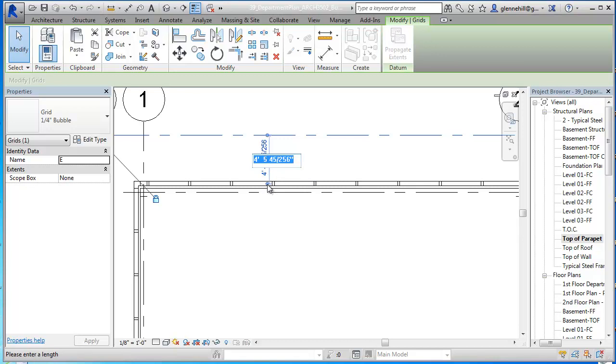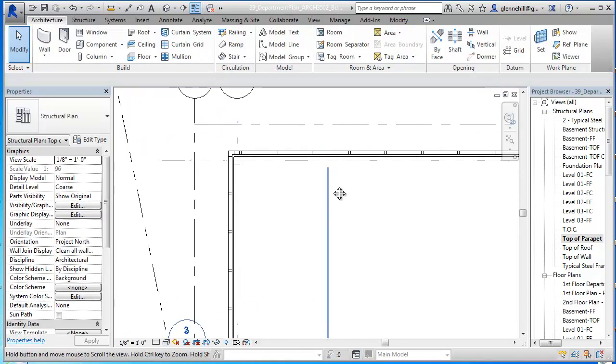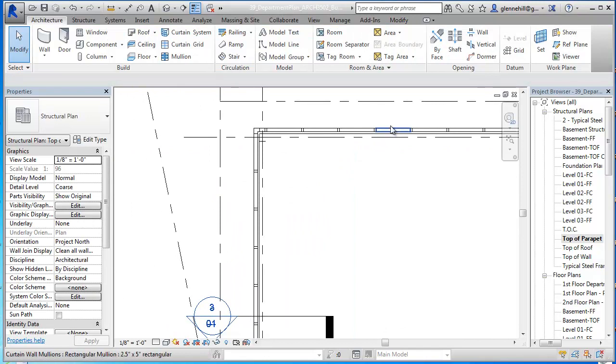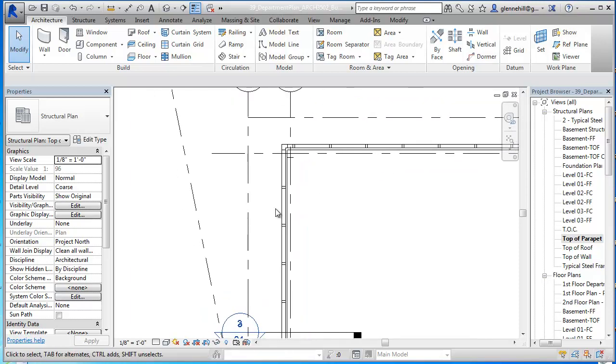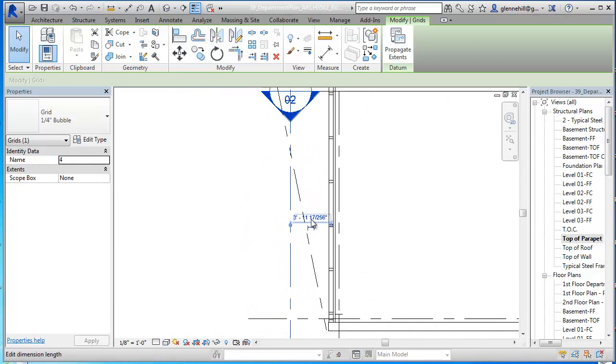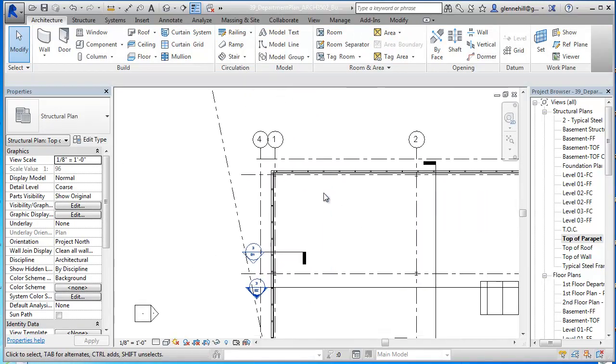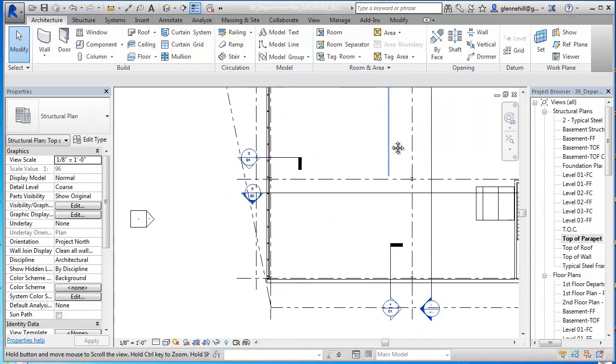I've got a little center line here to the window wall, so I'm just going to set that to 3 feet out from the center. So probably the clear distance is going to be around 30 inches or so. Now that may or may not be enough, so you can decide, check on it. There we go. There's a little dimension right there, so I'm going to do the same thing here. And so now I've got the location of my screen here on the outside.